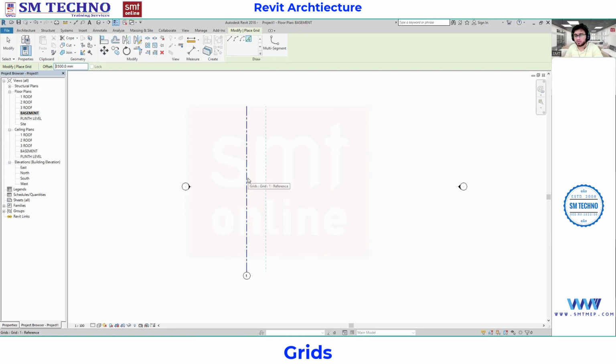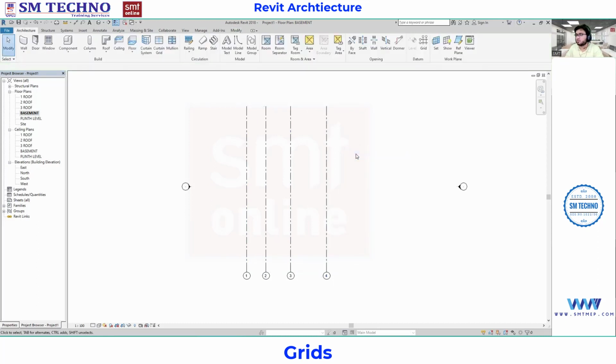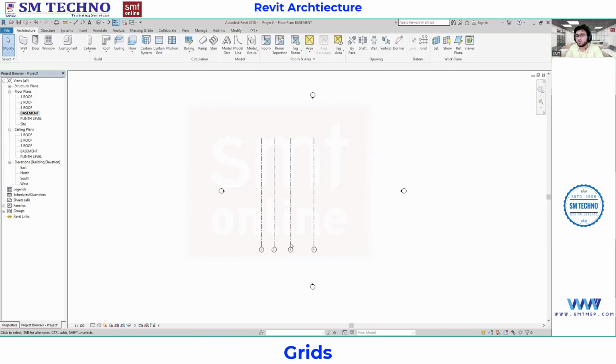Can you see here? If you keep the cursor on the right side, it will make an offset on the right side. If you keep it on the left side, it will make an offset on the left side. I'm going to keep it on the right side. Select this and it will make an offset. If you want to modify the value, like 4500, you can select and place from there. If you want something like 6500, you can select and place. Right click, cancel. So we have got the grids.